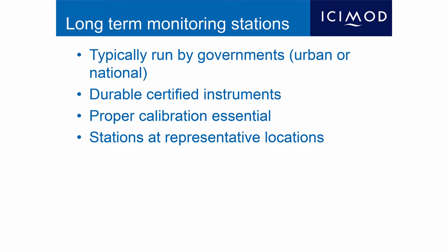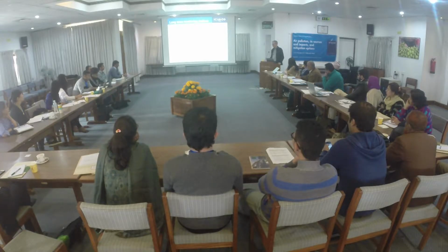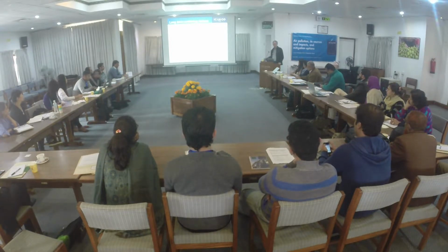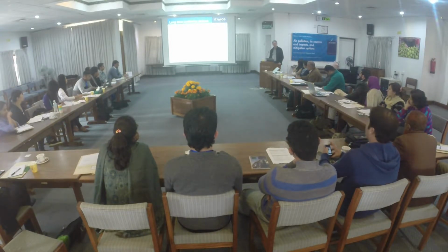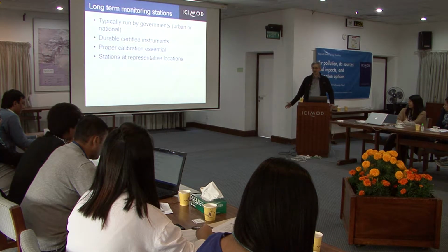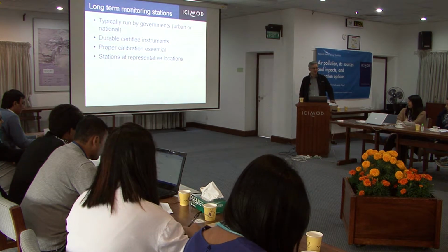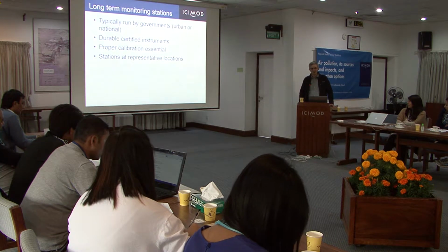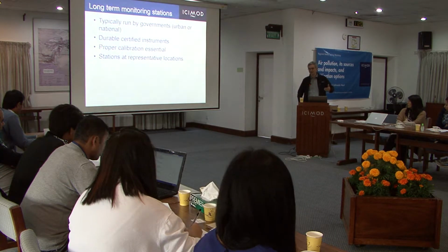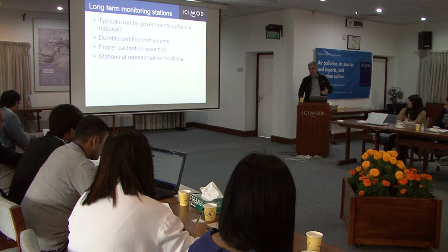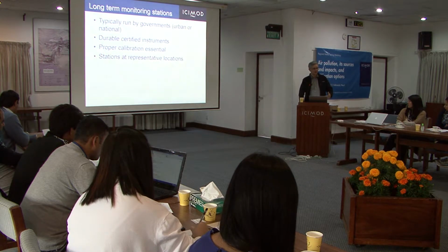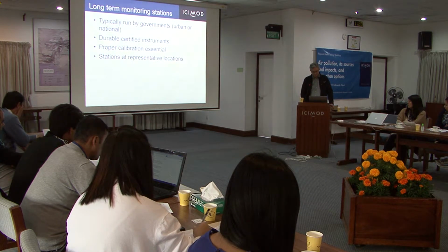It's making sure that if pollution is 0, the instrument's actually showing you 0 and not showing you 50 or minus 100, and that when, let's say, actual PM10 concentrations are 200 micrograms per cubic meter, the instruments are showing you 200 and not showing you 150 or 300. There are a lot of things that can knock off an instrument's accurate measurements, and so calibration is the act of checking and readjusting the instruments frequently to make sure that what they're measuring matches what you're looking for.